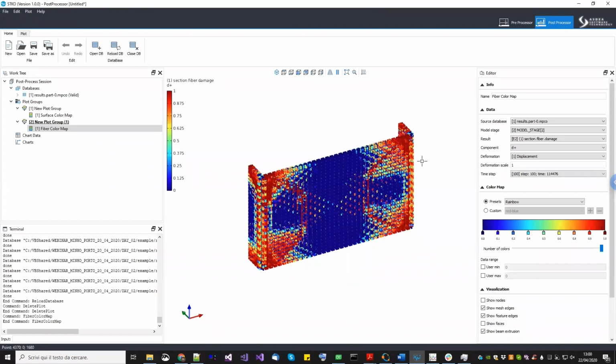So the displacement will never be completely continuous. And there is damage. So since you have a strain localization, this strain will localize into the dimension of the mortar joint. When people started talking about the plate bending theory, they were referring to the standard finite element method.